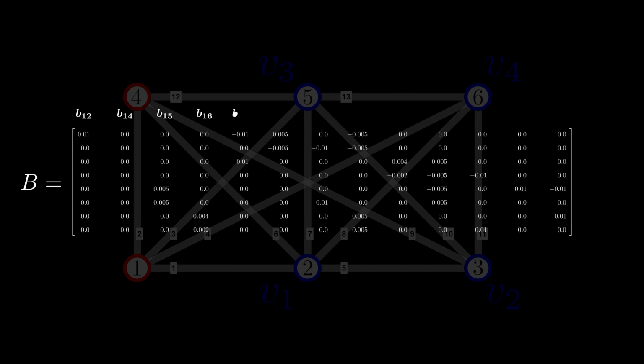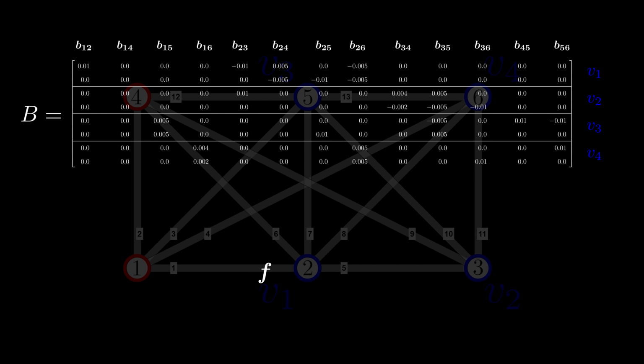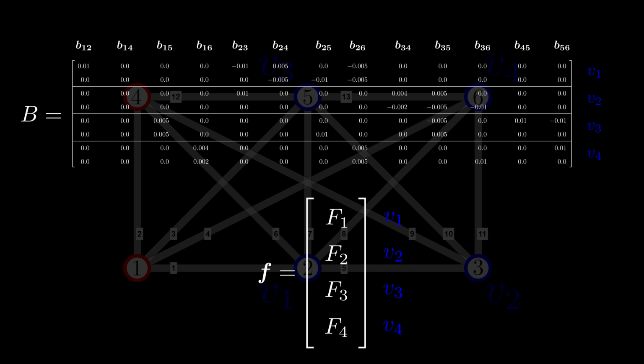The truss that you see in the background has a height of 1 meter, a width of 2 meters, and the corresponding unit used here is centimeter. And as I mentioned before, every free node V1 to V4 has 2 corresponding rows in each vector BVW. If you want to define a force that will work on this truss, you will have to define a vector with 8 entries. In this case, the vector F is made up of 4 vectors from R2, F1, F2, F3 and F4, and what this means is that the force F1 will be applied to the node V1, the force F2 will be applied to the node V2, and so on.